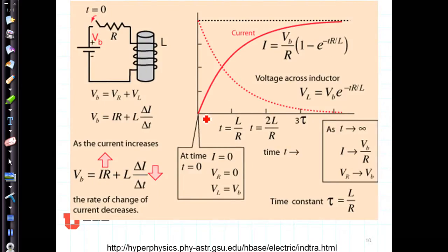This is what happens to the inductor. The current basically starts out at 0 and gradually rises to its full total value. The total value for current, remember that the inductor would be a short circuit in that case, would simply be V over R in its final state. The voltage, on the other hand, does change quickly. It goes from 0 to all of a sudden going up to a maximum value and then dropping on down. The maximum value of this voltage is the source voltage.